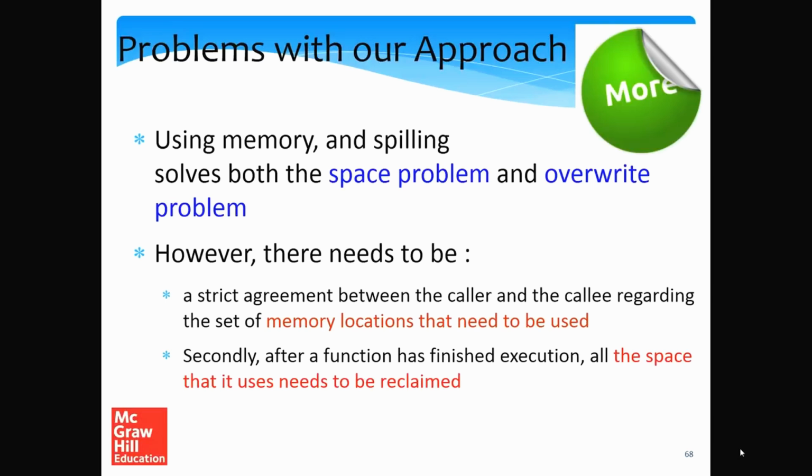The main reason being that we only have 16 registers. Out of that, we will see that we are typically not allowed to use more than 14 for general purpose work. So let's say one function calls another copy of itself or other functions, then they will overwrite the registers that they require, because all of them see the same view of the register space.